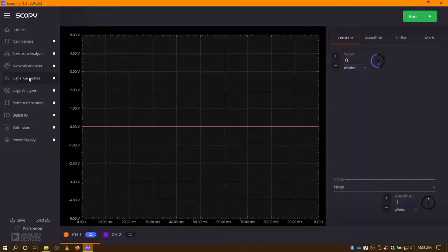That's within spec. When you look at the software, you realize you can go further than that, but they're only going to guarantee the plus or minus 5 volts and the 5 megahertz. Over that, you may be pressing your luck, and later on when we get more in depth I'll show you what can happen when you try to exceed those values.